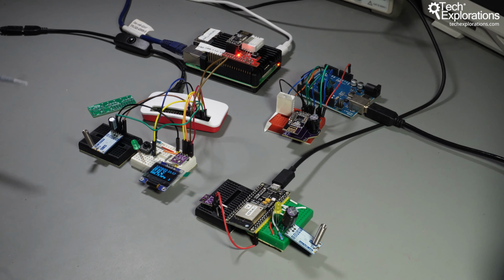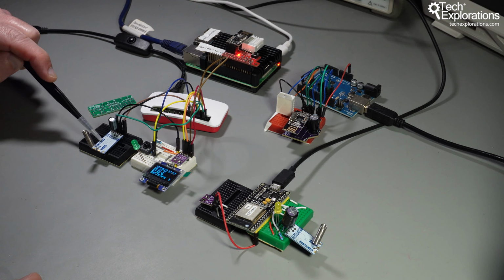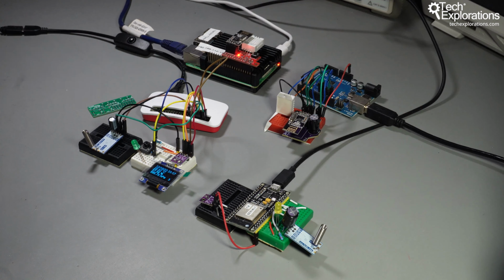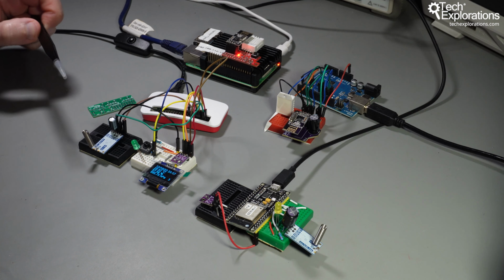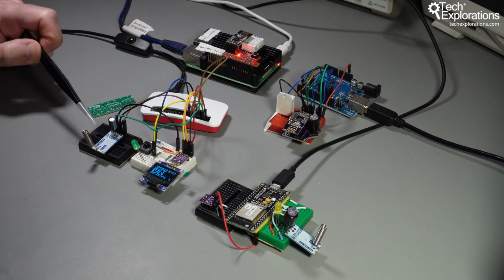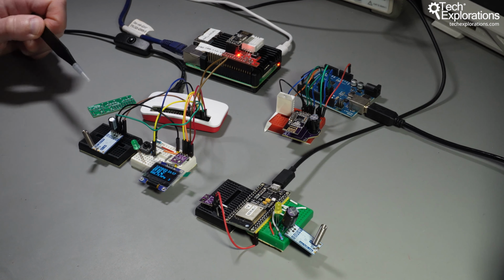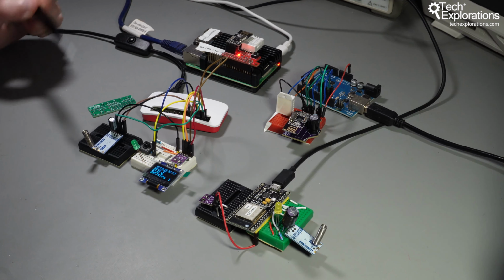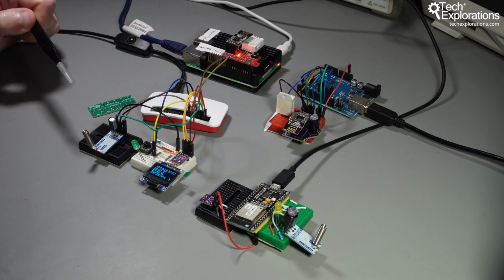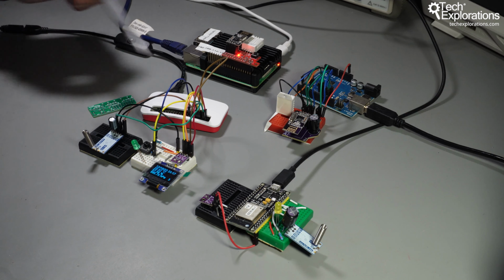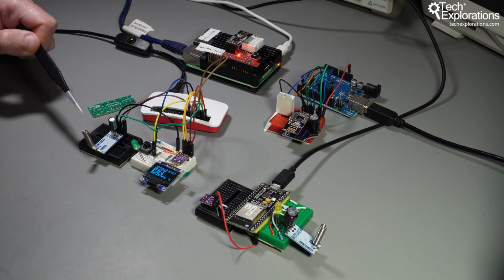In terms of communications, I'm now using the HC12 on both sides. I've got an entire section dedicated to the HC12. It's a really good, really reliable radio communications module. It uses the same frequency as the RF24, but it is now serial. So I'm using the UART serial interface on the ESP32 and on the Raspberry Pi. Very reliable, configurable. It doesn't have all of the bells and whistles of the RF24, but for the purposes of our application, it's more than enough.